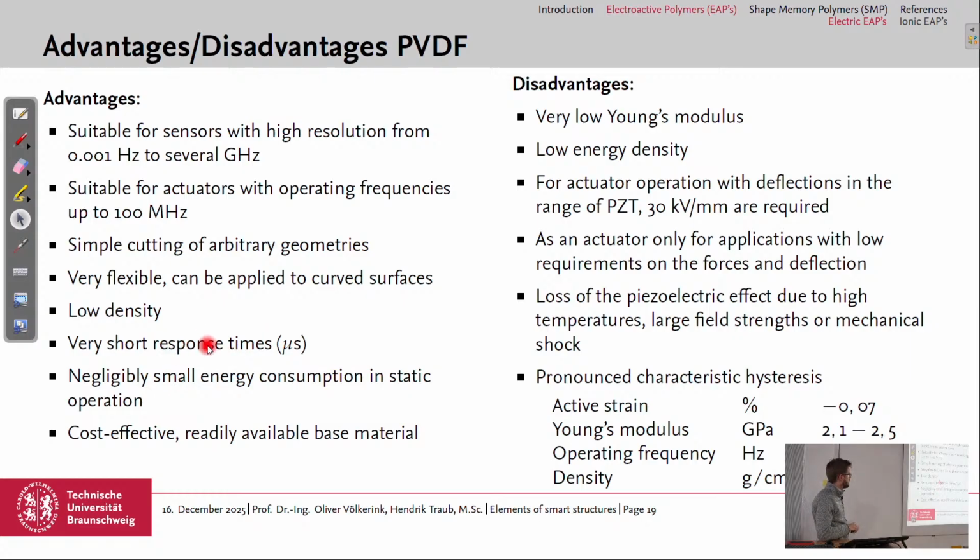Very short response times, therefore it's good as a sensing material. It has again a small energy consumption like the piezoceramics, and it's cost effective and readily available. You can commercially buy it. But it has a very low Young's modulus of around 2 gigapascals, also low energy density.